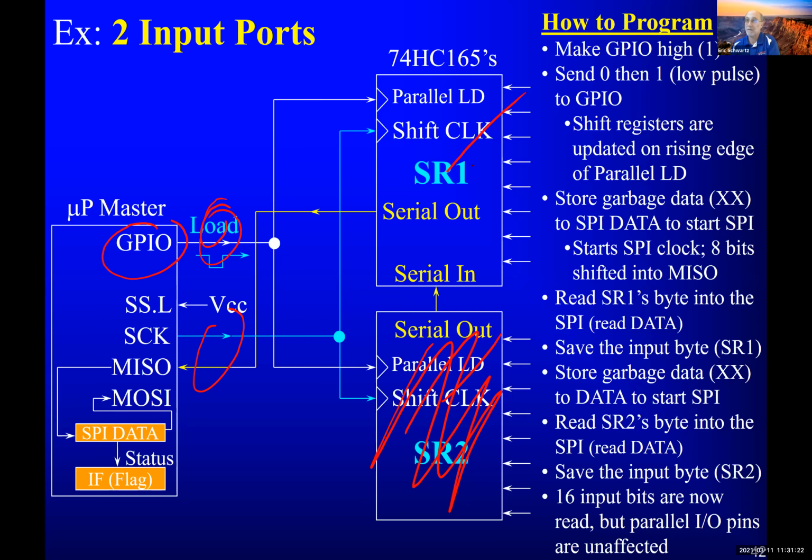Okay, so SPI is preferable if there's no other choice, which is quite often. Probably half the microcontrollers out there, maybe even more every day, don't have a bus. They don't have data and address bus and control bus. They don't come out. They're internal. And they do this because they say, what more do you need? I'm a microcontroller. I got every piece of memory you need. I got timers. I got serial capability. I got everything you need.